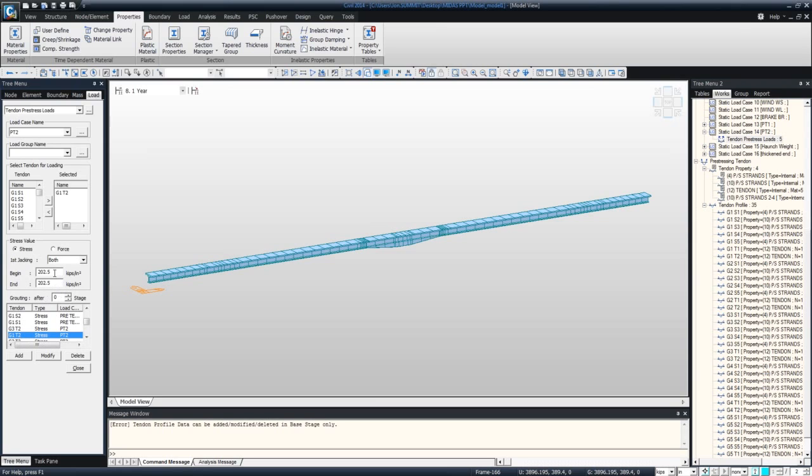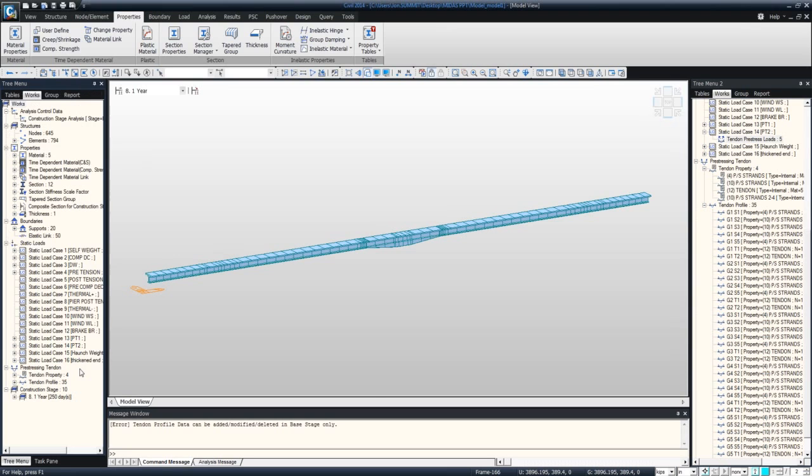In this case, I'm stressing from both ends to 0.75. This also gives me the option to stress from the beginning or just the far end. In this case, I will be doing from both. And then what I'll do here while I'm on pre-stressing strand is pause quickly, jump back to this effective model we had.